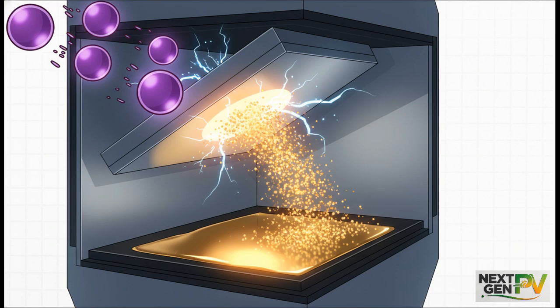First, we put our target material and our substrate into a chamber and draw an extreme vacuum to suck out all atmospheric contaminants. Next, we pump in an inert gas, almost always argon. Argon is the superstar here because it's heavy enough to act as that perfect cue ball for momentum transfer.